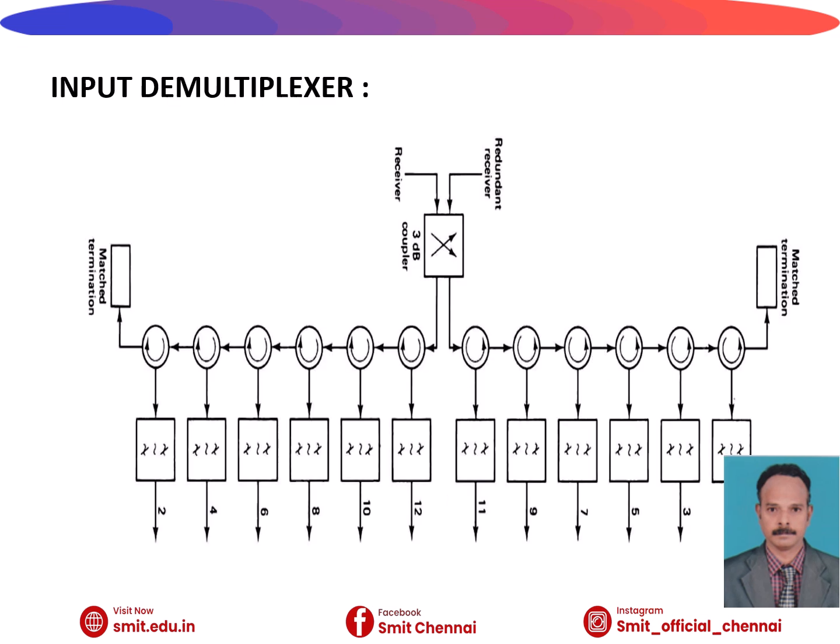So why do we not amplify excessively? Too much amplification may cause saturation, distortion, or intermodulation products. That's why we cannot extremely amplify. Generally, we will use high power amplifiers in satellites, particularly two common amplifiers, namely TWTA and SSPA. Both are widely used. TWTA is nothing but the traveling wave tube amplifier.